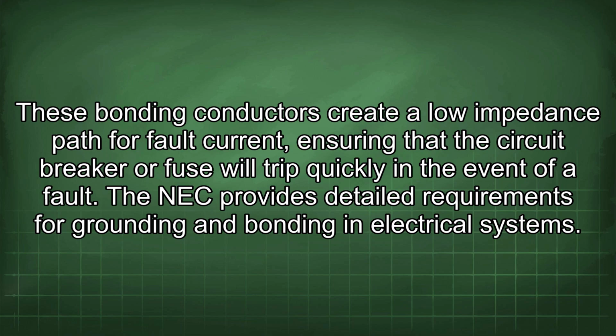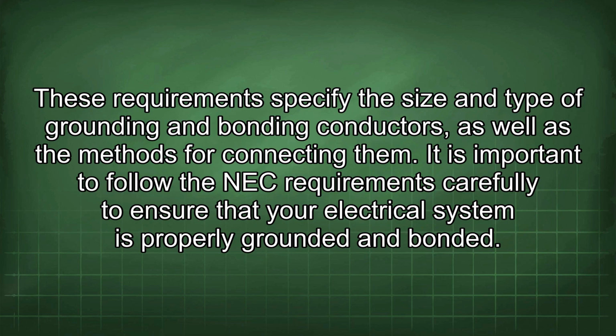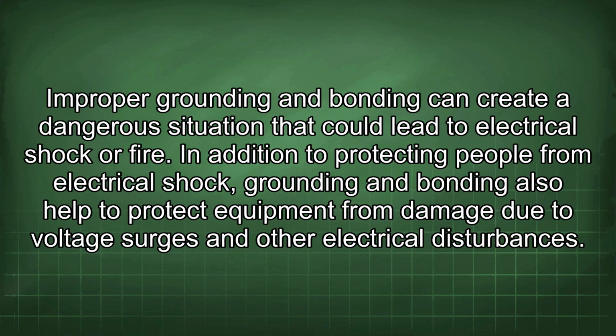The NEC provides detailed requirements for grounding and bonding in electrical systems. These requirements specify the size and type of grounding and bonding conductors, as well as the methods for connecting them. It is important to follow the NEC requirements carefully to ensure that your electrical system is properly grounded and bonded. Improper grounding and bonding can create a dangerous situation that could lead to electrical shock or fire.